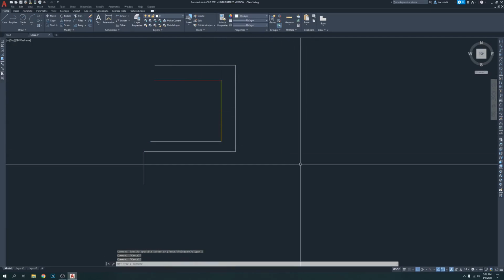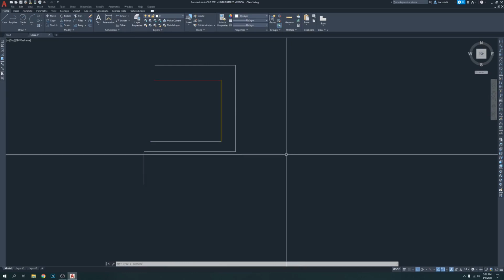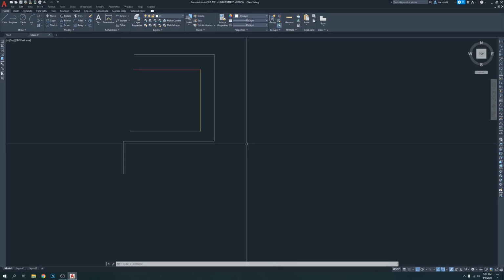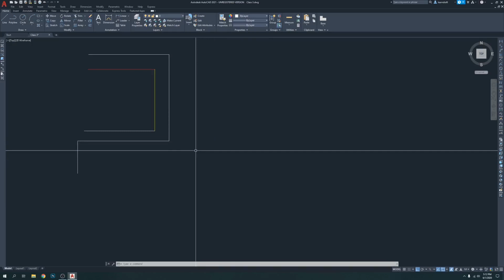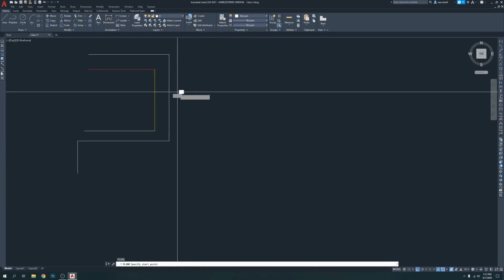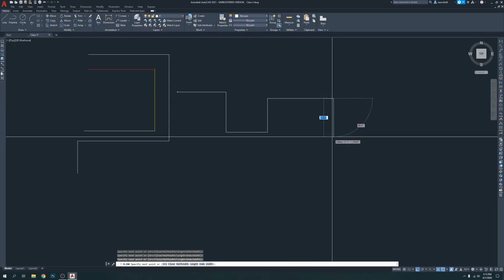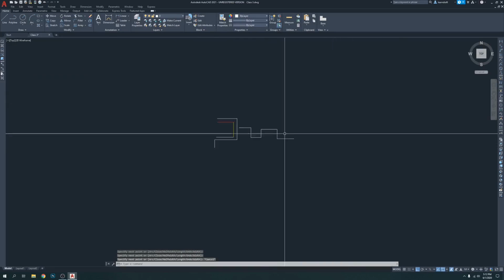Can you see this? You see these 3 different lines, we can join them together. This is different, this is time consuming, but we need both. Sometimes we need line, sometimes we need polyline. So I don't want to make too much of it. So polyline, how to draw polyline? PL, enter, click, click, click, click, anywhere you go, click, and it's going to follow you.